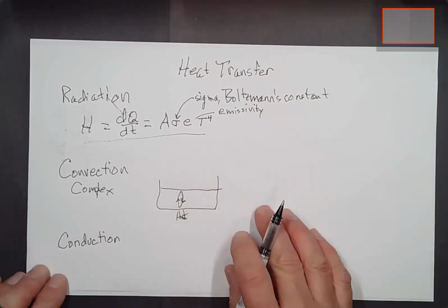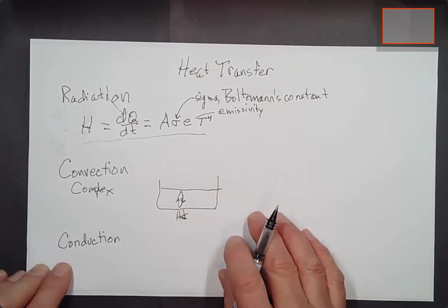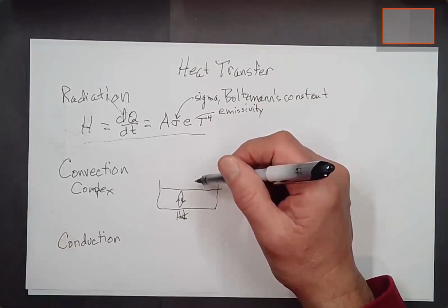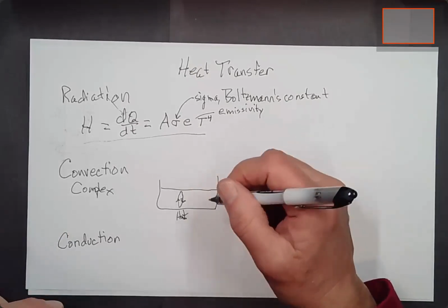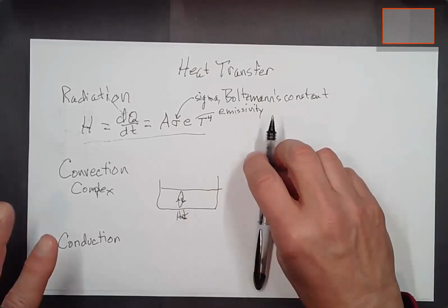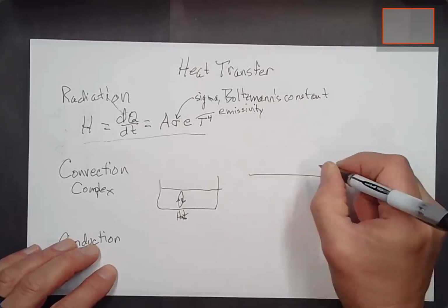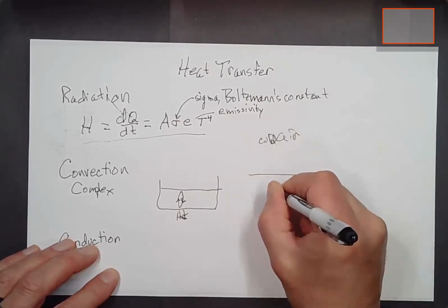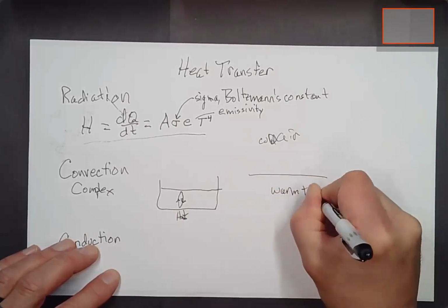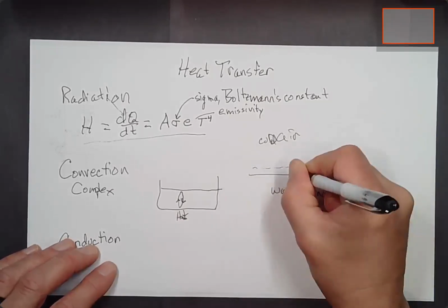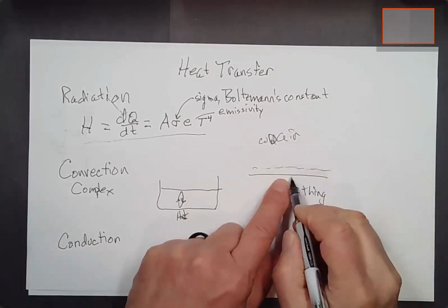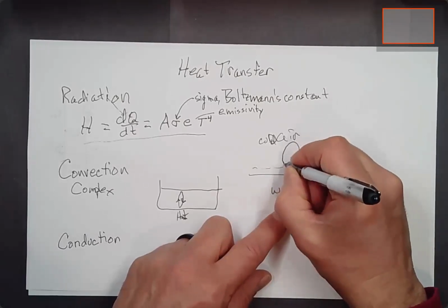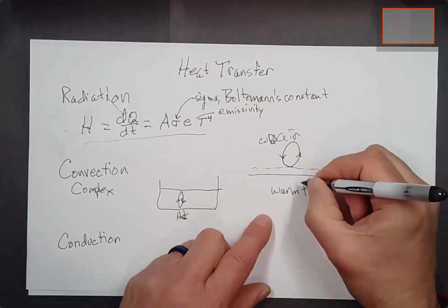So that's about all I'm going to say about it, except, because of fluids having a viscosity, which is a resistance to flow or a resistance to move, you can usually have a surface film at the surface of something where there isn't any convection taking place. So, like if you've got air up here and maybe it's cold, and down here is some warm thing, there will be a small zone right near the surface of the thing. If you had a convection current right here, it would run into friction at the surface of this object, and there's less friction when you get above it. So here you might have convection currents with a small gap between them and the warm thing.